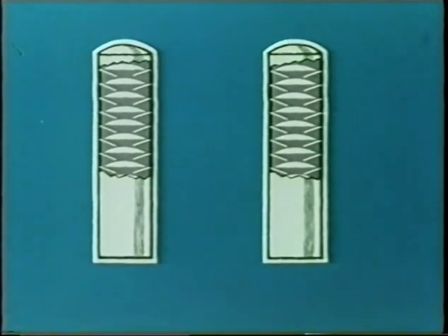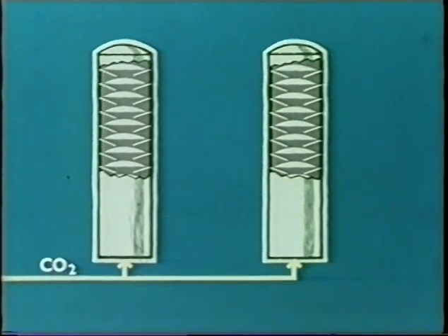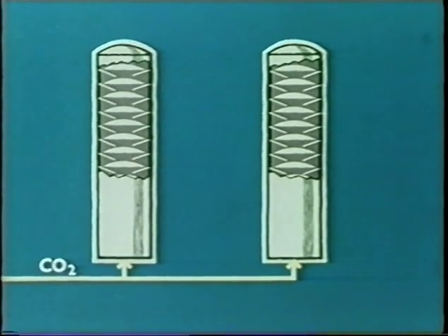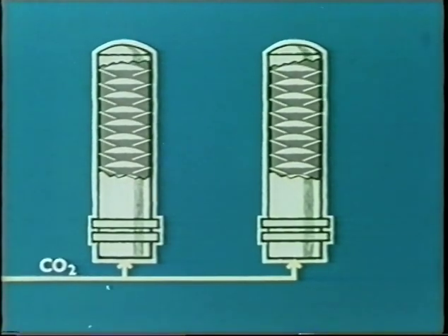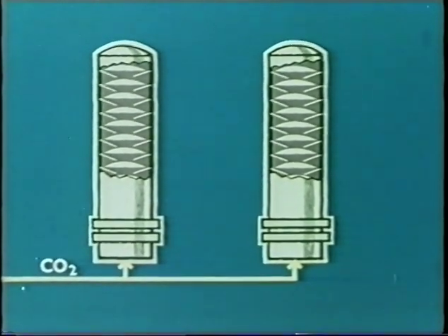All is now ready for the Solvay Towers. There may be dozens of these, worked in groups of towers which are interchangeable. All the towers contain a series of baffle plates. All have inlets at the bottom for carbon dioxide gas from the kilns. They have water cooling boxes to take away the considerable heat generated by the combination of carbon dioxide and ammonia.